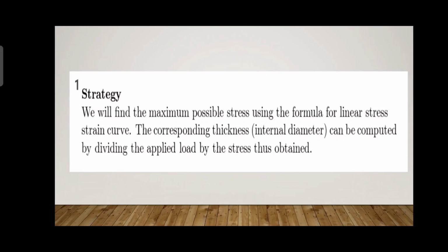First strategy will be to find the maximum possible stress using the formula for linear stress-strain curve. The corresponding thickness and internal diameter can be computed by dividing the applied load by the stress thus obtained.